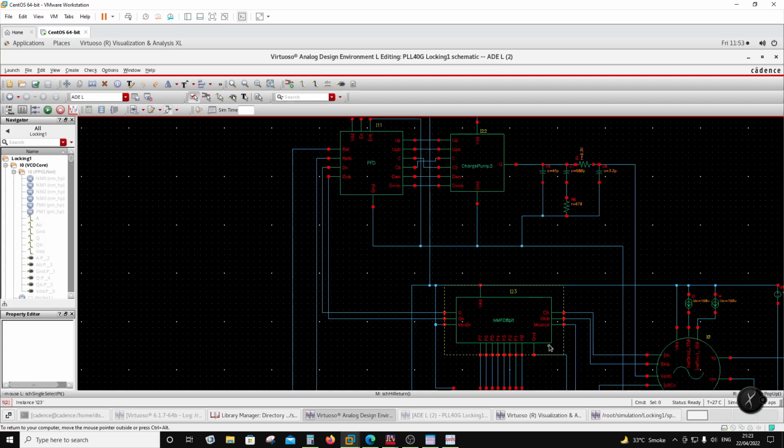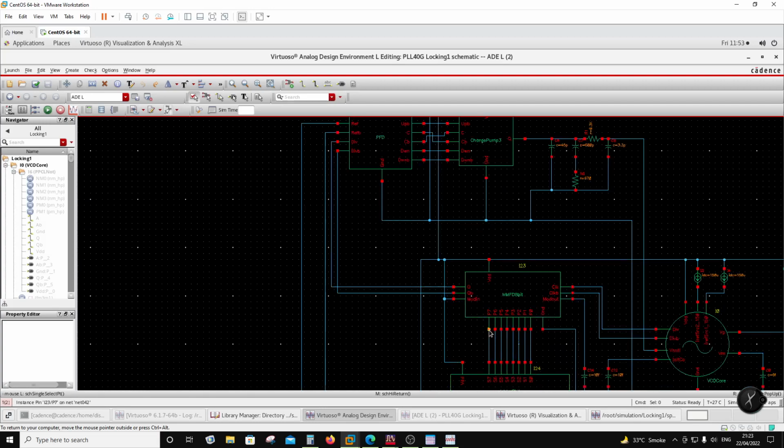Now, the point to note here is the following. The 3 bits which come from sigma delta are added to the coarse count. Now, this has to be a fraction, not more than 10%. Reason is your PLL, if you give it a step input, which MASH will give it. Okay, if MASH count goes from 0 to 7, so basically there are 8 states, and those 8 states are added to the count, right? So 8 states in 400 something count is less than 10%. That's what I'm trying to say.